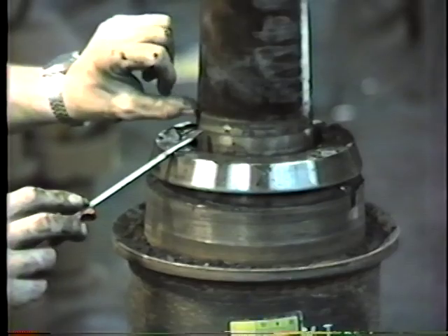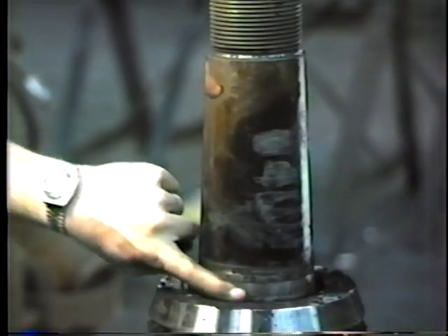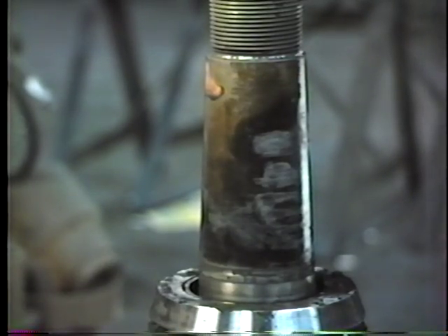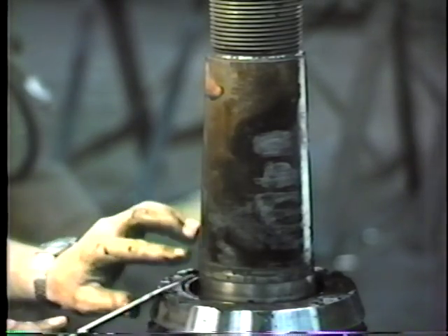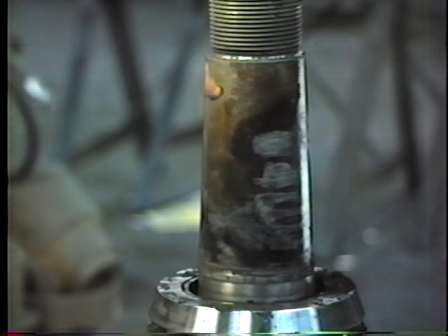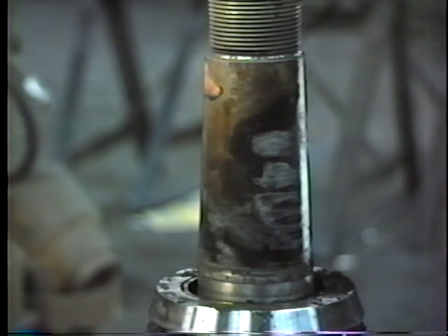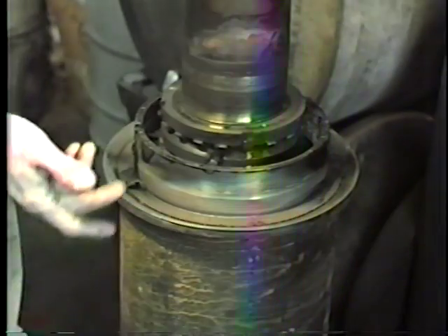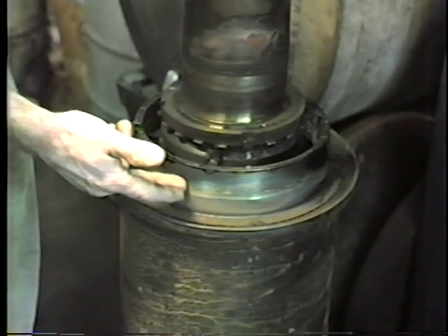The shaft is discolored, one color here and another color down below. The upper portion, does it look straw colored? Right. Would you say that this has been overheated? I would say it was. Alright, looks like a temperature problem. Okay, thank you, Bob.